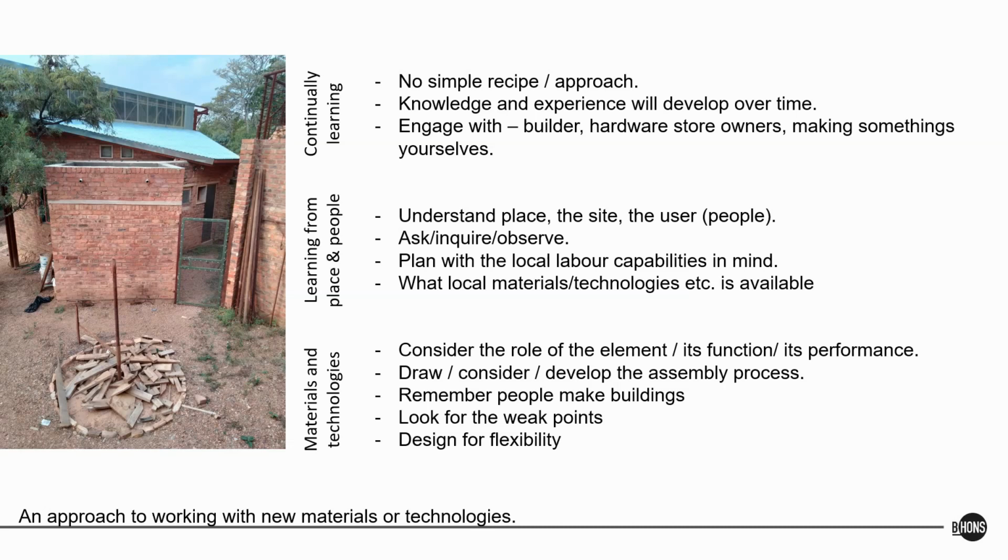Okay, I'm designing this, but when do I need to be on site to check it? Can I remove a panel, or can I ask for something to not be in place so I can check whether that's in place? A typical example: the engineer needs to check whether the steel reinforcing has been bound and bent correctly before you cast the concrete, obviously. But for an architect, there's a number of others, because you have to check a lot of other different aspects in the end.